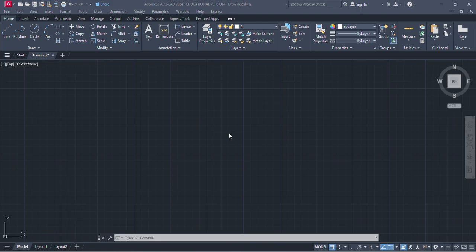First, the initial settings are done, which you can learn from the previous videos. Now I'm going to create an A4 sheet, taking a 10 mm margin from the A4 sheet. Originally the A4 sheet is 297 mm lengthwise and 210 mm widthwise. So I'm taking a margin of 10 mm from both sides, length and width.